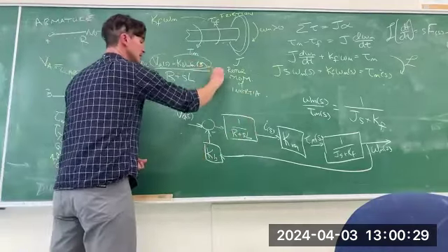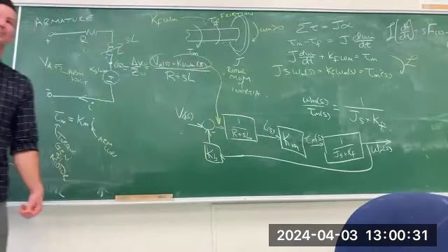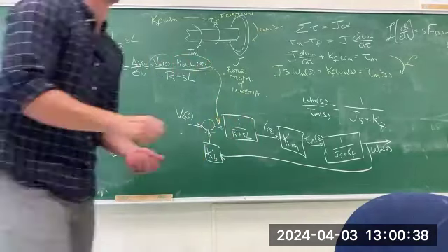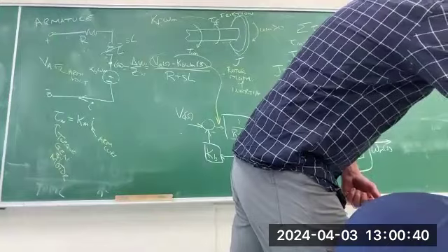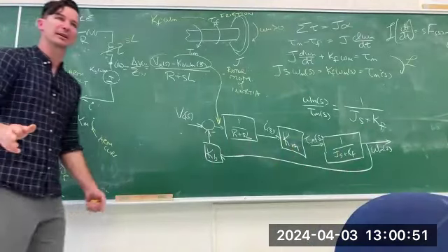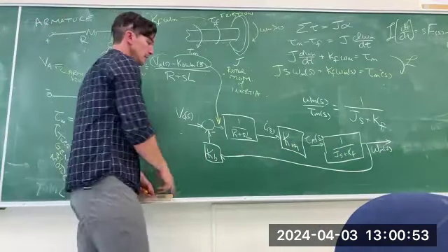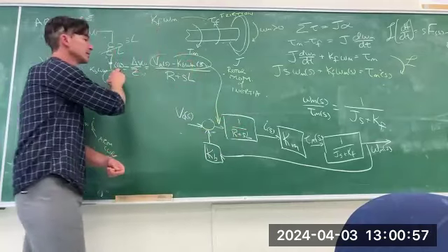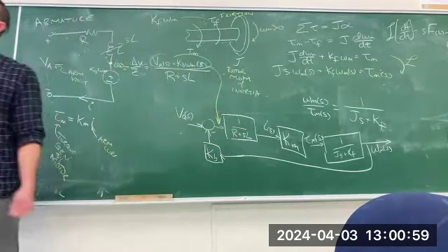This is this signal, which again isn't really the error, which is why I think that this DC motor is one of these systems. There's feedback, but nothing's being controlled, right? We're not setting a set point or anything like that. So this numerator is this. If I divide that by this guy, I get the current, and then we can close the loop.